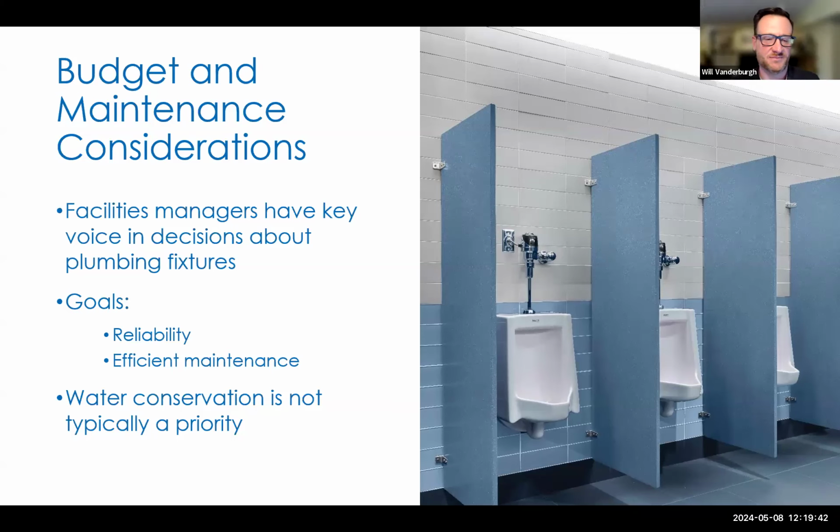In some faucets, you're able to program them so they operate with a set cycle time. Typically, 20 seconds would be the norm. But we found when there's high traffic times, you're able to shorten that to 10 or 15 seconds. That actually helps move people through the washroom more quickly. So an adjustable cycle time is a great benefit when you have a particularly busy washroom.